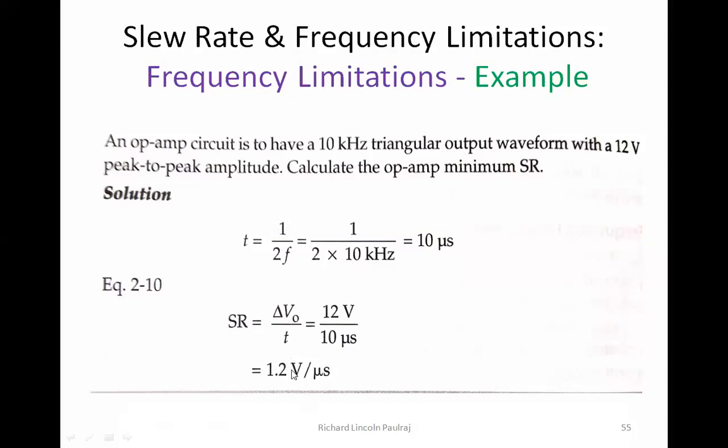This volts is here and per microseconds is also here, so you just have to divide 12 by 50. Fine. So 0.24 volts per microsecond, what do we understand by this? For every microsecond change of time, there is going to be about 0.24 volt change. What voltage change? Is it the input voltage change or the output voltage change?